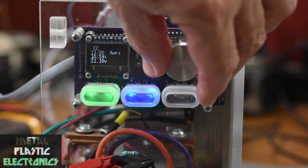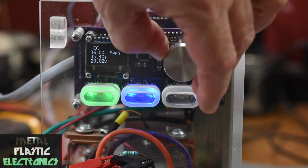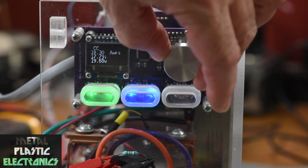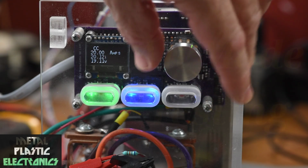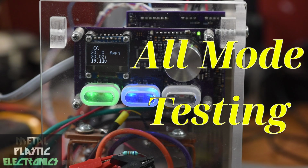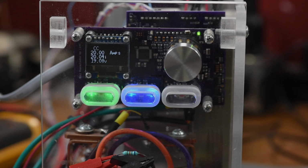With the constant current mode just about there, I want to get a bit of a temperature correction going and get the other three modes operating. I don't think the constant voltage and constant power will be much of a problem. Constant resistance, on the other hand, I have a feeling when I get to that I'm going to wish I had used a processor with hardware floating point math, but I'll find out in a bit.